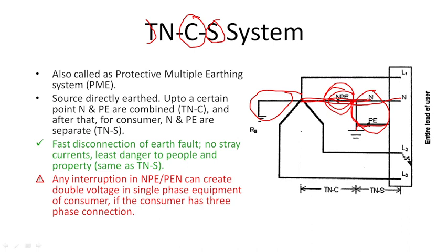In case of a three-phase system, if neutral breakage happens, there is a chance that double the normal phase voltage, or more than double, may appear across a load. This mainly happens like this: consider a three-phase system, with R, Y, B phases. You have a small LED lamp or LED bulb or your mobile phone charger, which is 5 watts, connected to the R phase, and you have a heater connected to the Y phase. If your neutral is there, the phase voltages will remain the same.